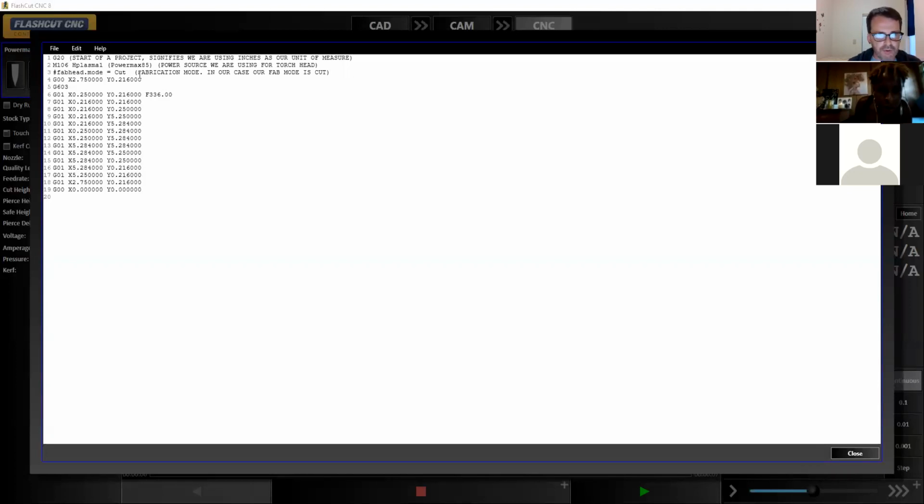Just means that we're in cut mode. Okay. We're going to put another line in here. G00, X0, Y0. And this is our point of origin. This is where we want the torch to start and end every time we make a drawing.